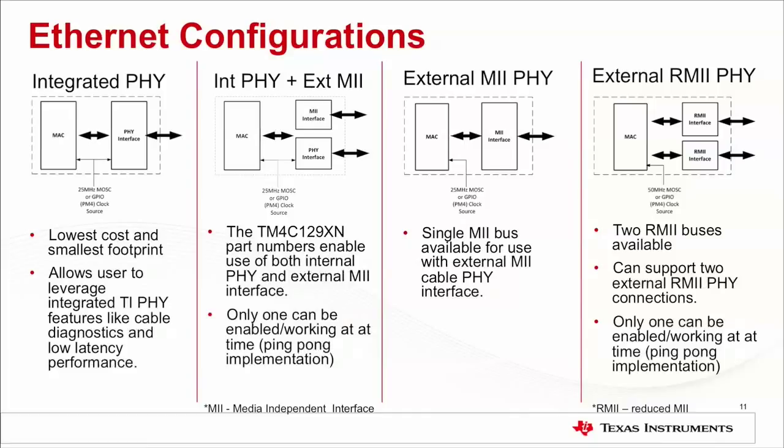If you need to connect a special PHY, such as the one with optical interface, you can choose parts that provide MII interface. However, if you have a really fancy application that requires connection with multiple PHYs, you can choose parts with RMII interface.